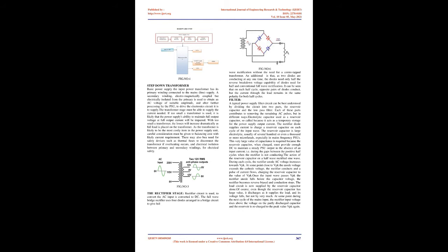The transformer stage must be able to supply the current needed. If too small a transformer is used, it is likely that the power supply's ability to maintain full output voltage at full output current will be impaired. With too small a transformer, the losses will increase dramatically as full load is placed on the transformer. As the transformer is likely to be the most costly item in the power supply unit, careful consideration must be given to balancing cost with likely current requirement.